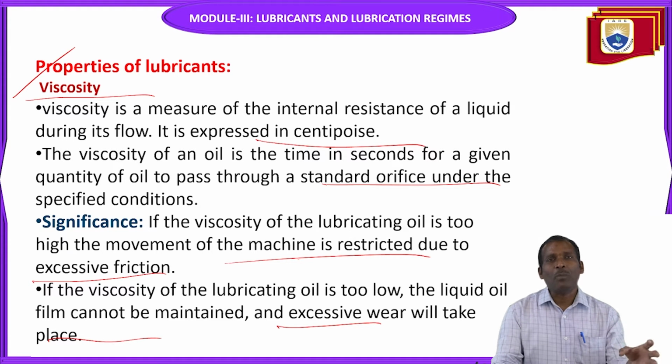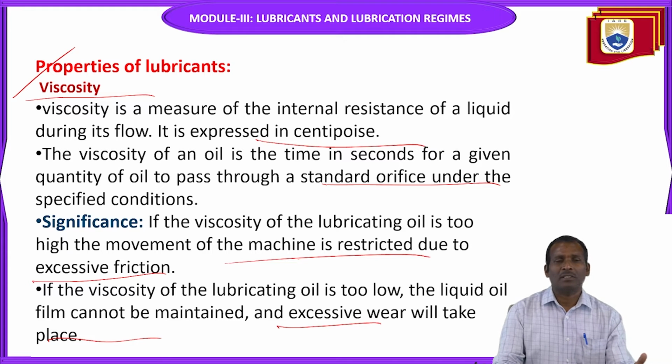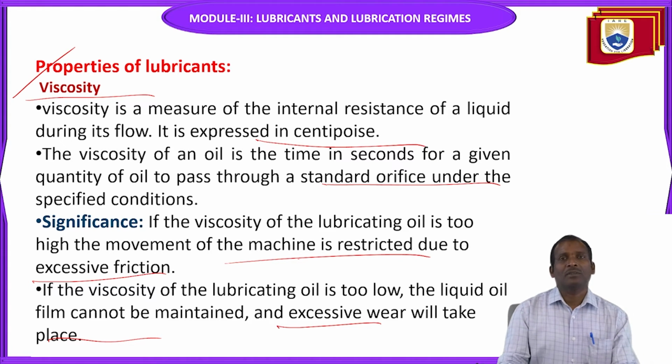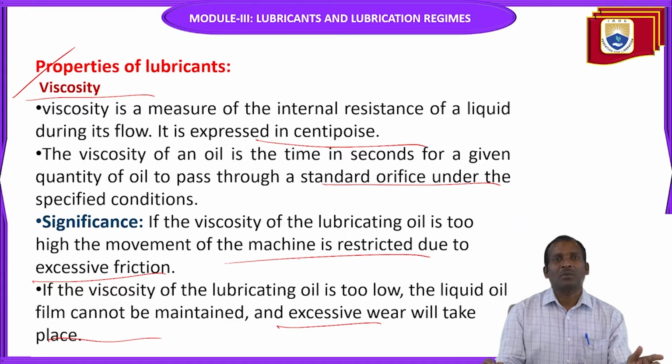That's why you should maintain the proper viscosity. Clear. If you do not use the proper lubrication for the proper application, the results will not be favorable. The lubrication oil viscosity depends upon the load, the type of material, and the type of application. According to the application, you have to select the lubrication oil grade.